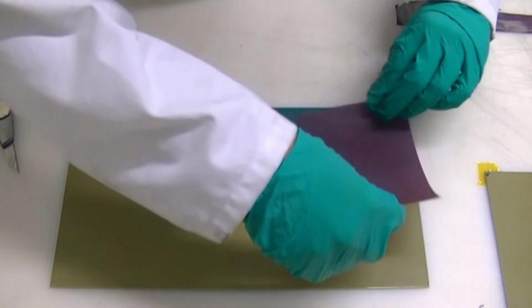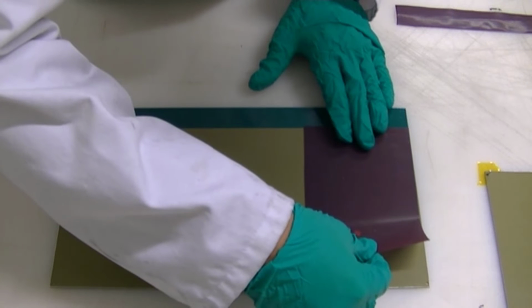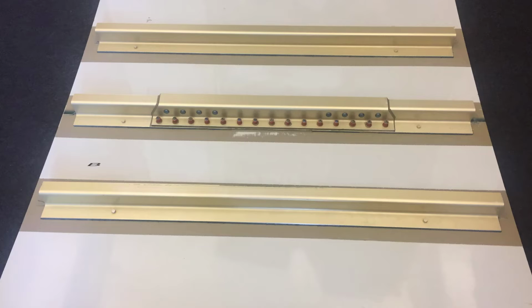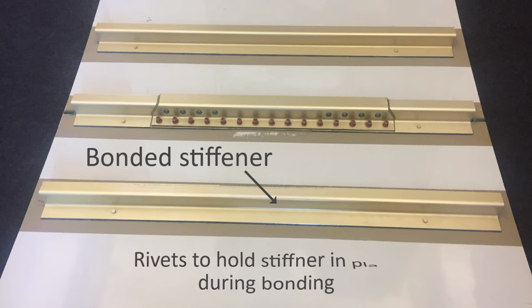The next step is to apply the adhesive material to the parts to be joined. The adhesive material can come in many forms, including an adhesive film or paste that can be applied on the surface of the part. Once the adhesive is applied, the parts can be assembled and temporarily held in place with some form of clamps or fixtures. This is an important step as the adhesive cannot carry loads until it has fully cured, forming all the necessary chemical bonds with the surfaces of the parts.